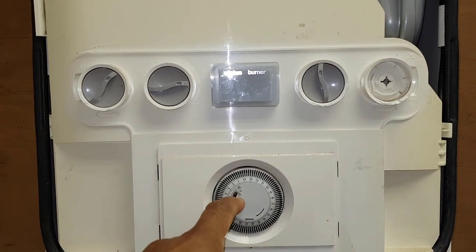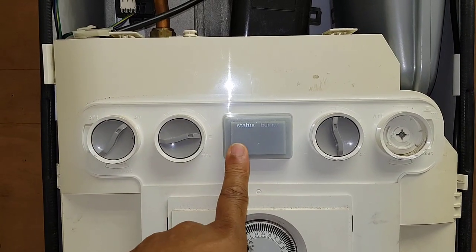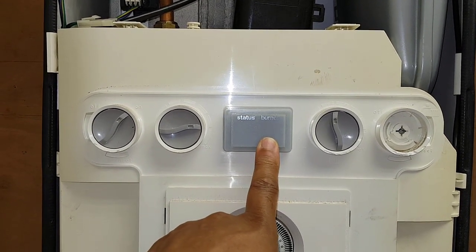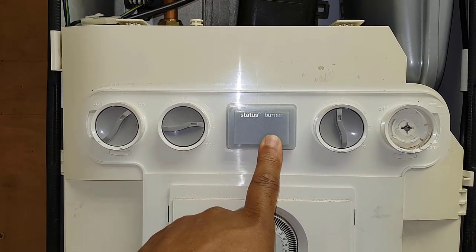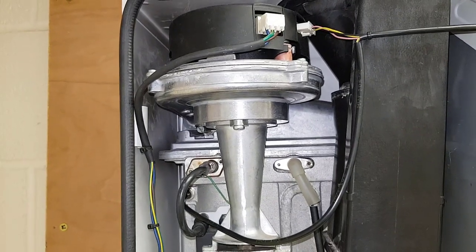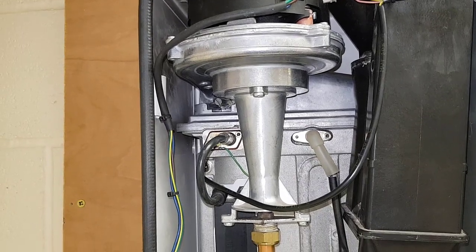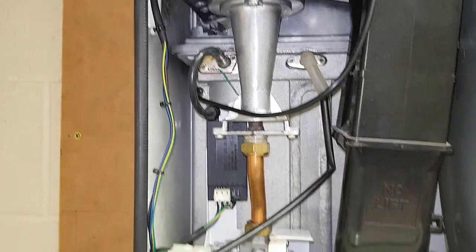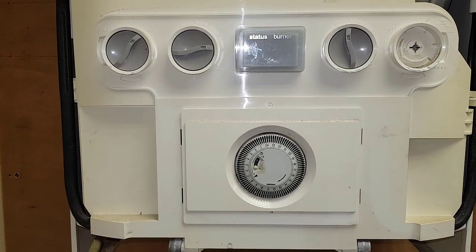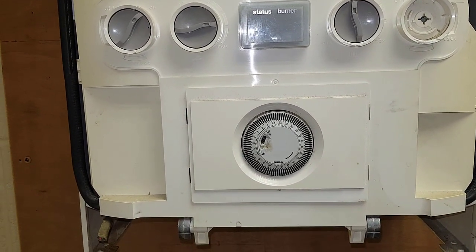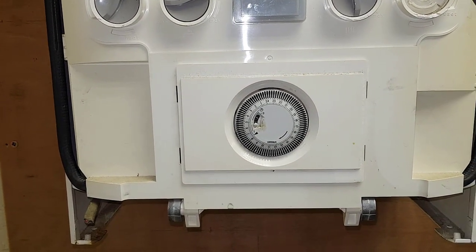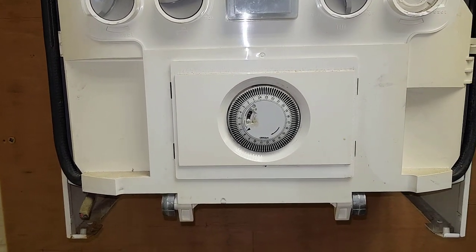You can turn on the room stat, C will come on, the burner light will come on, but it'll go off after about a minute. What you'll hear is the fan speed rev up and then reduce down, and then probably go off to nothing. Using your ears, you listen for the fan speed, and if it starts diminishing, you know that something's getting too hot too quick.